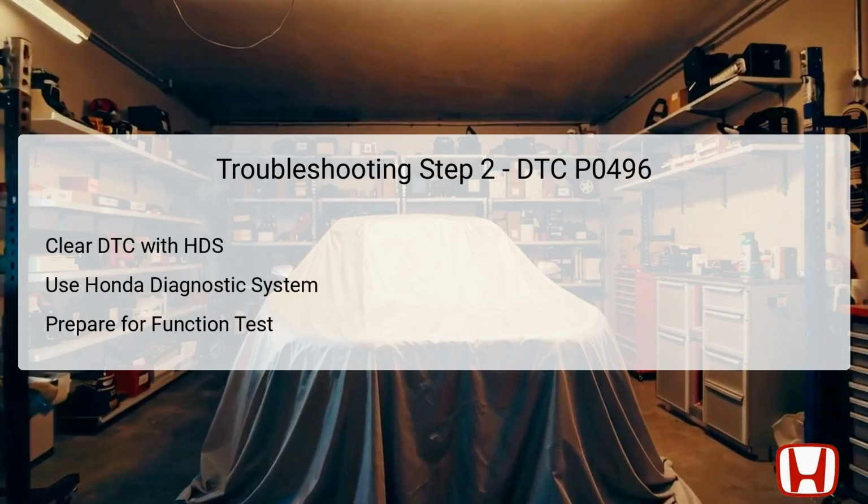In the second troubleshooting step, the technician should clear the DTC, Diagnostic Trouble Code, using the Honda Diagnostic System, HDS. Clearing the DTC resets the system, allowing the technician to start fresh without historical codes affecting the current diagnosis. The HDS is a specialized tool designed for Honda vehicles, enabling detailed analysis and testing of various systems.